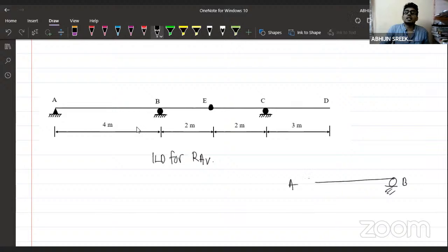First of all, we need to release the vertical reaction at A. This is how we will be releasing the vertical reaction. After releasing the vertical reaction, I have to give a unit displacement in the direction of the released force component, the force function. The reaction was in the vertical direction. I have released it, now I have to give a unit displacement, and I have given a unit displacement. The structure will come here. We are having a roller there, right? The structure came here. So now this is the beam, and this displacement here is 1 unit.